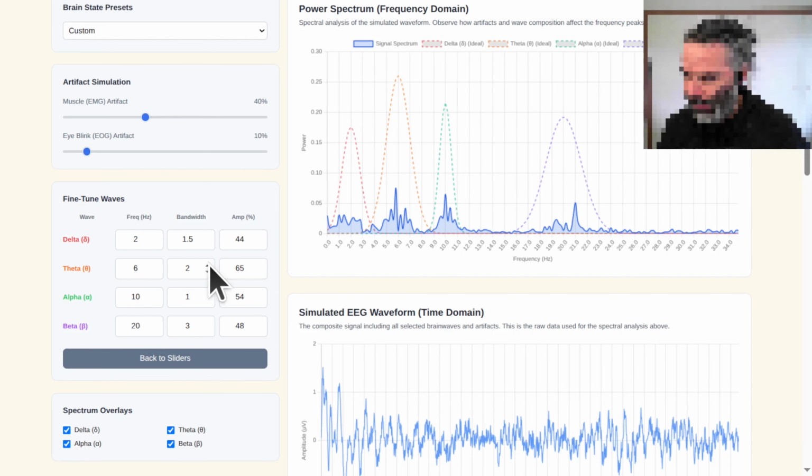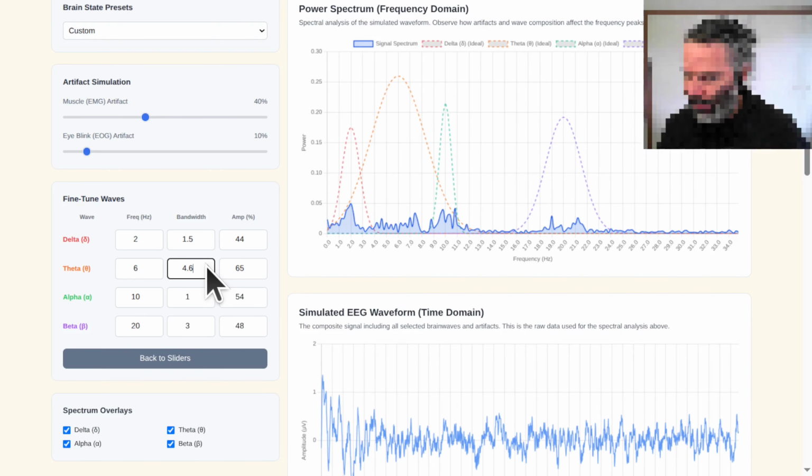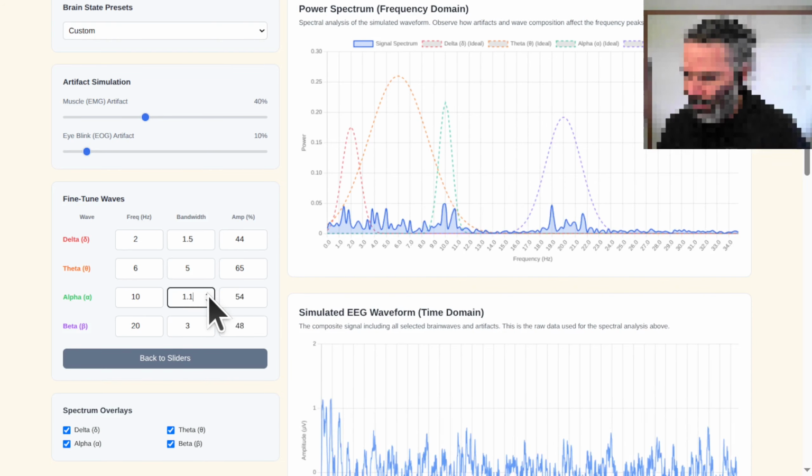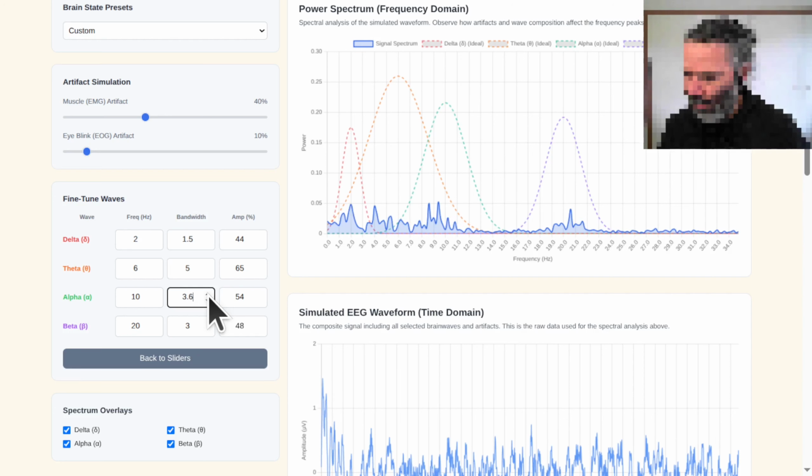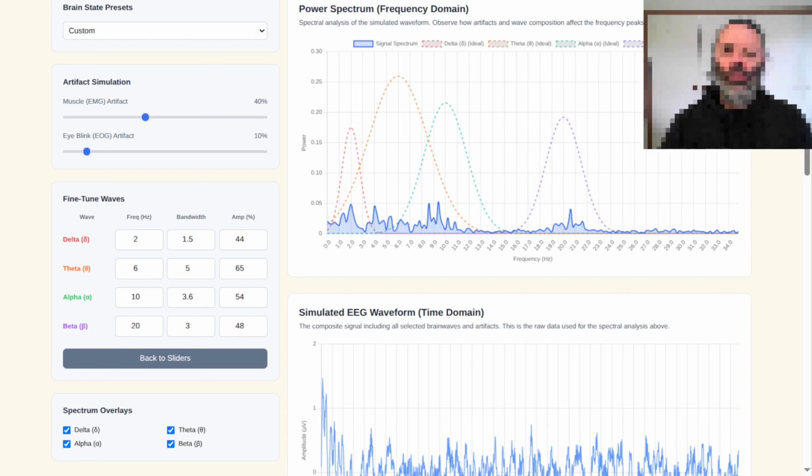Okay, so you set everything up with the controls. Then you look to the right at the visualizations. The top one is the power spectrum. That's the frequency view. Correct. It's showing you the output of a fast Fourier transform, an FFT. Basically, it takes that wiggly line over time and breaks it down, showing how much power, how much energy is at each specific frequency. You'll see peaks where you're...